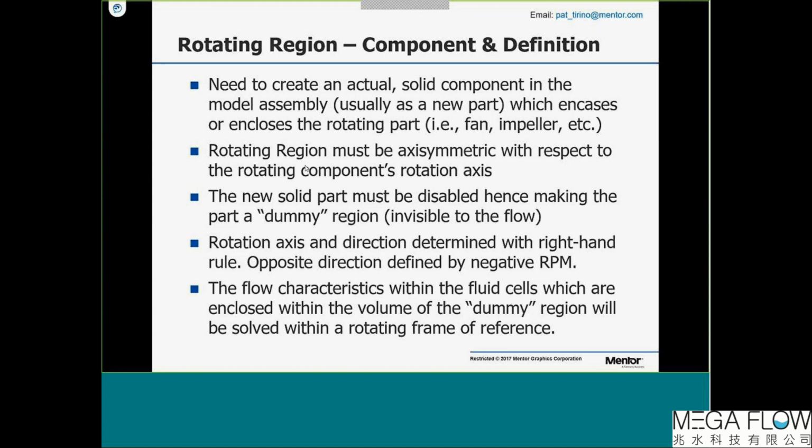But at the same time, the volume of that dummy region, that dummy part, can be used for something like this. It can be used for letting EFD know that the cells that fall within that volume are being solved for in a rotating reference frame. Okay, that's how it knows which cells are being applied this rotating reference frame.